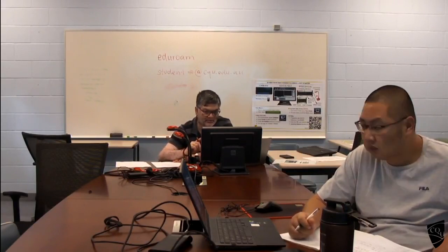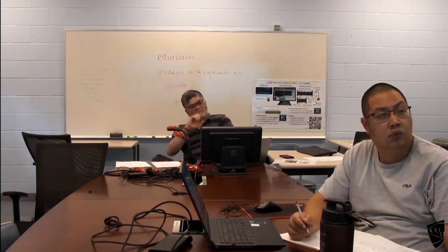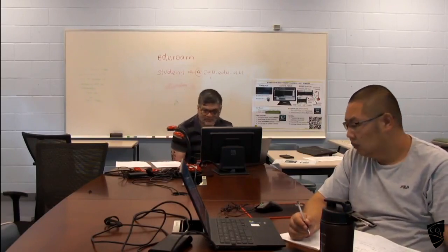In edge panels only one side is discontinuous. But here you can see the longer side is discontinuous, and here the shortest edge is discontinuous. So depending on where we are sitting, we may have two different edge panels.